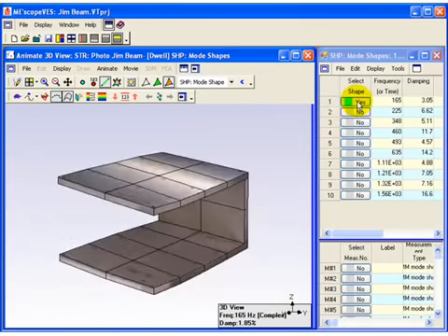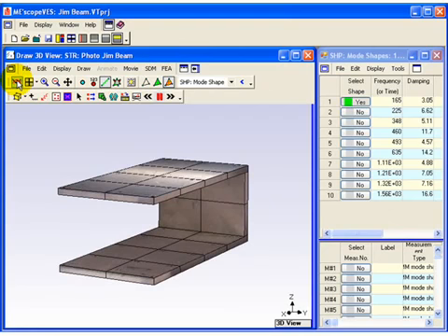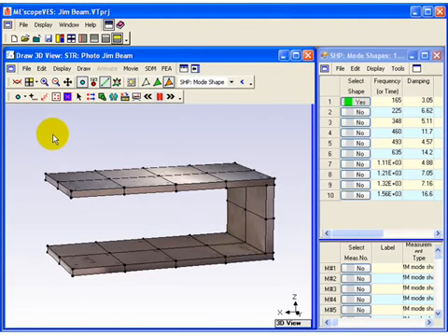To create a 2D profile, execute Animate, Draw to terminate the mode shape animation. Select Points from the Edit Object list of the Structure window toolbar. Hold down the Control key to enable Draw, click Select, and select points on the photo model to define a 2D profile.